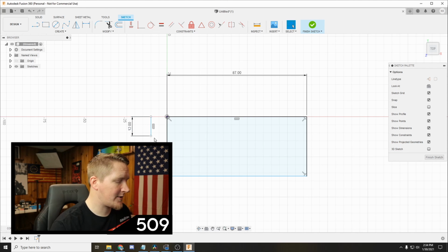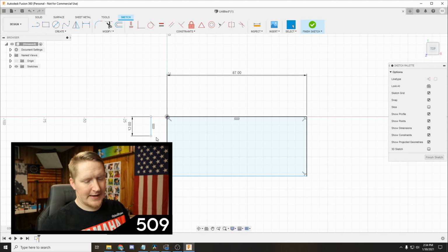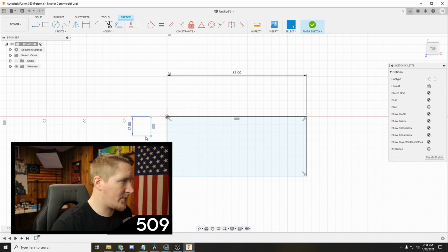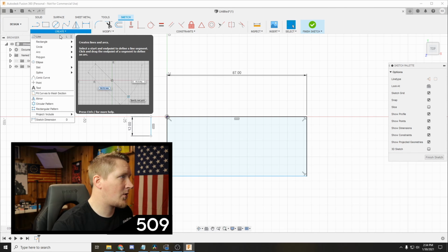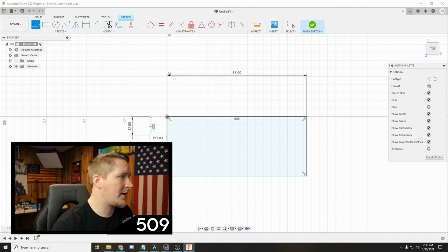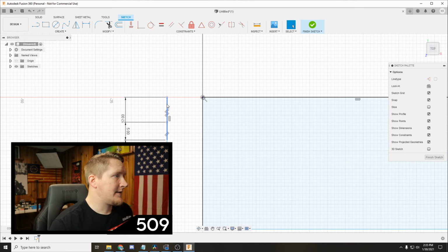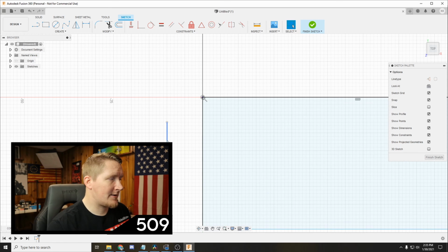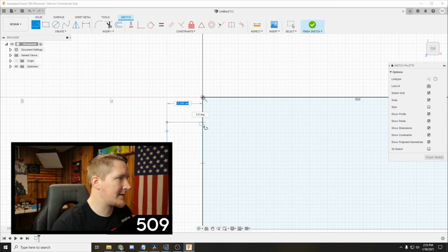That's where the center of this hole is, and we're going to say it's 10 millimeters wide. So I'm going to go down 5, because that's the center. Create line off the center, up 5. Then we can delete these extra lines. This is a 10 millimeter line offset off of, I already forgot how far I offset it. And then I would just connect it to there.